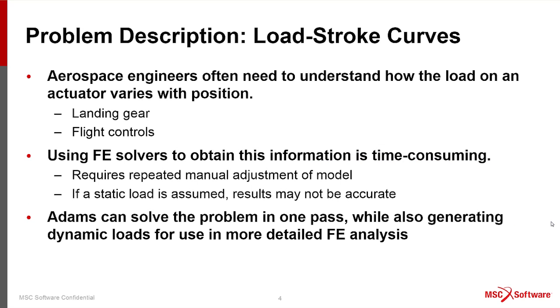This problem of developing load stroke curves is something we encounter with things like landing gear design and flight controls. It's a really familiar problem. We need to understand how the load on an actuator is going to vary with position. Sometimes our motivation is that we need the straight-up loads for stress analysis on components. Other times we're designing a control system, and we want to know something about the kinds of loads we're going to encounter when designing that control system.